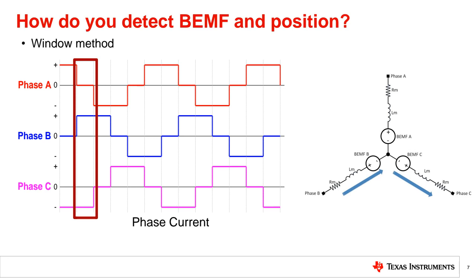Again, the voltage on phase A, for example, we can return to estimation. When the motor is in a commutation step, the voltage on phase A can be read with an ADC to determine what the back EMF voltage of the phase is. This back EMF voltage can then be used to determine when to commutate the motor. Most algorithms use the zero crossing of back EMF to determine where to commutate the motor. This zero crossing is when the back EMF crosses 0 volt.